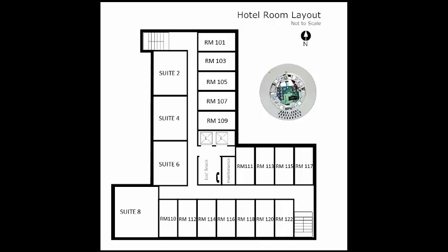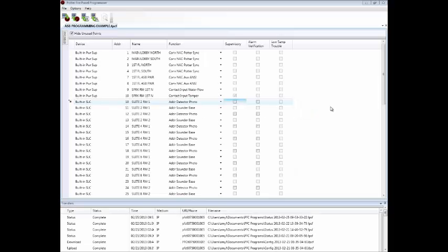There are also smoke detectors in the hallways as well as notification in the hallways that activate on a general alarm. General alarm is triggered either by pull stations or water flows in the building, as well as smoke detectors in the common areas or hallways. In this example, we will just be looking at the sounder bases and how they are programmed into this type of scenario. In this particular example, I have already done some setup in the programming software.